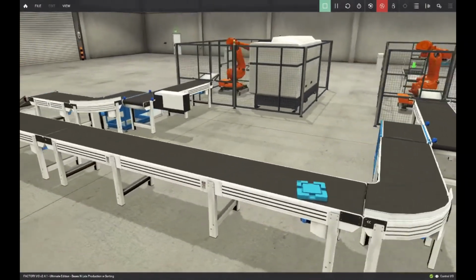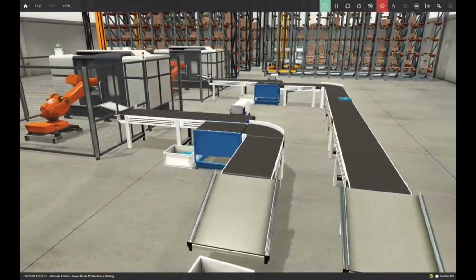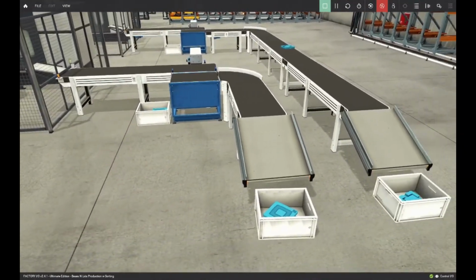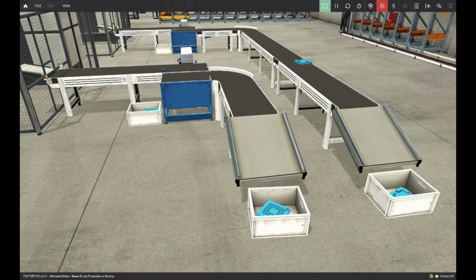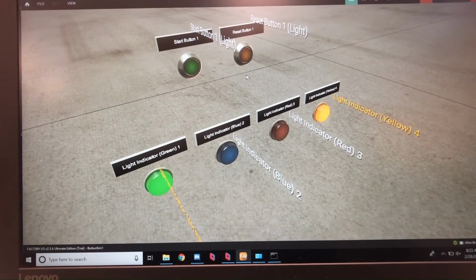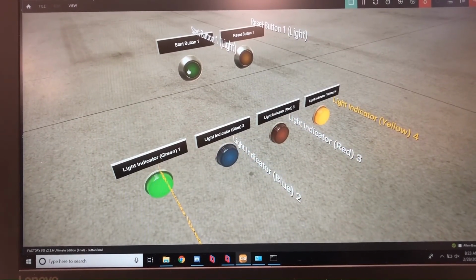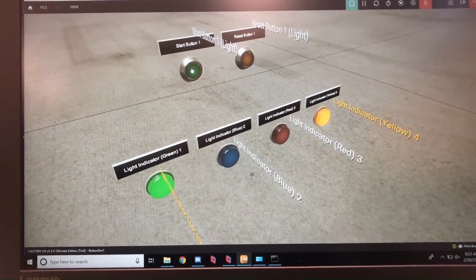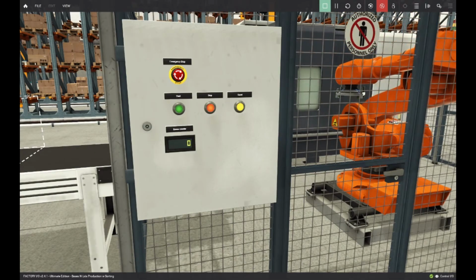The tests of the PLC can be done in two ways inside Factory I/O. First, a representation of the process can be recreated using the many parts Factory I/O has to offer. A second, much quicker approach would be to arrange an array of buttons and lights to represent the PLC's inputs and outputs. Analog values can also be represented in Factory I/O using the digital display. Here, we see the display being used to count the number of cycles ran.